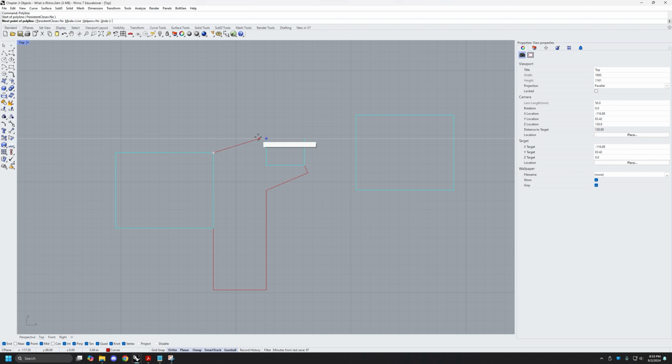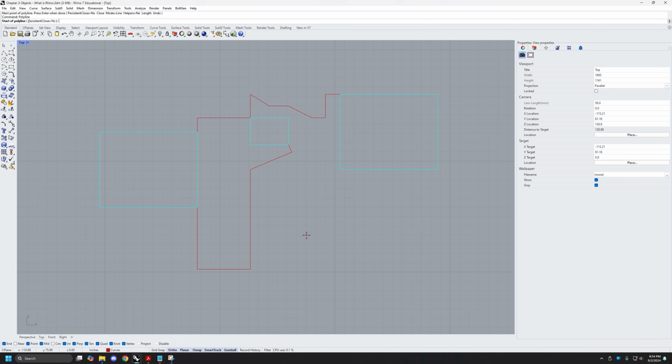So experiment with that using polyline. You can quickly find these little reference points and create some pretty accurate lines, movement types, pressing the tab key, right? Maybe it's this midpoint I want to reference, and then I want to go over to this point, right? I hope this is showing you how powerful this tool can be. It's very, very useful for creating precise geometry that references other nodes in geometry. So use the tab constraint to create those custom points.